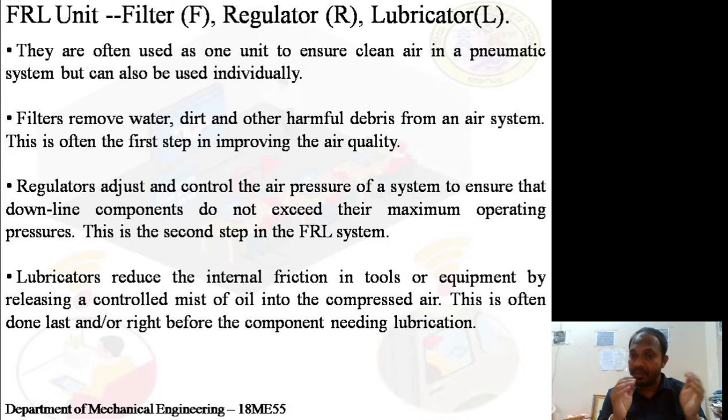Okay, now first and foremost is the filter which we are placing before the compressor. It is only because the compressor is drawing the air from the atmosphere, and in the atmosphere there will be a lot of very minute dust and dirt particles, or it may be sand particles. Many things will be there which have to be filtered before it enters into the compressor. Now this is the first point where it increases the performance of the compressor.